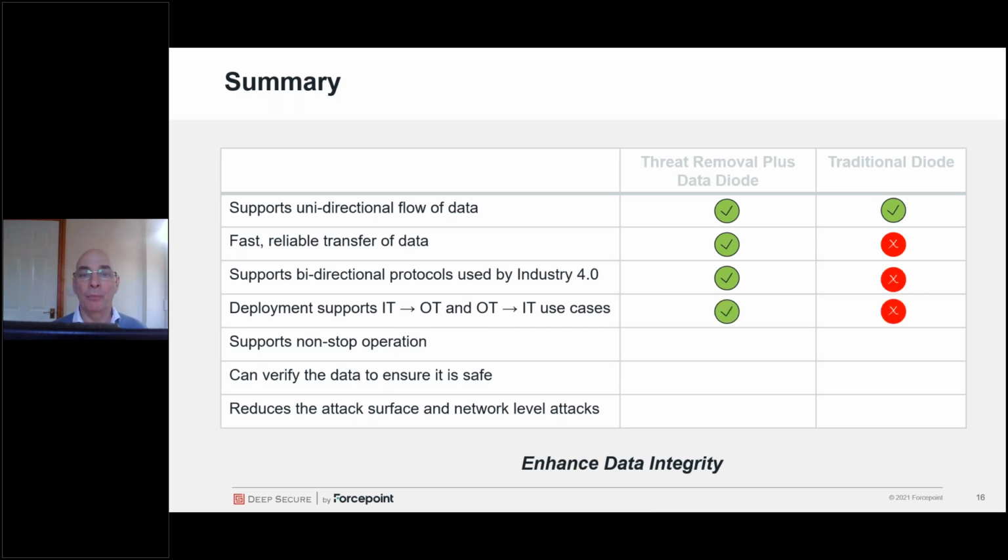This is a multi-purpose diode, so it's capable of handling both IT to OT and OT to IT use cases. It's designed for non-stop operation, with high availability and failover built into the very fabric of the design. And as a threat removal diode, it's capable of verifying that the data it carries is safe, for example by constraining it to predefined schemas. Because that verification is performed in hardware using FPGAs, it can't be remotely compromised by an attacker. And what that gives is a massively reduced attack surface.